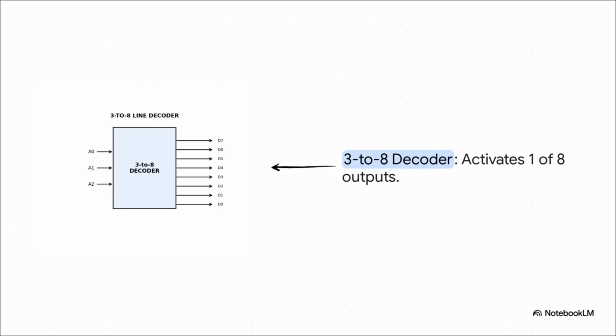We're going to treat these next few components like digital flashcards. First step is the decoder. A decoder takes a small binary input and expands it, activating exactly one corresponding output line. Say you input a binary 3, well, output line number 3 lights up. In the real world, these are often built using NAND gates to keep manufacturing costs down.